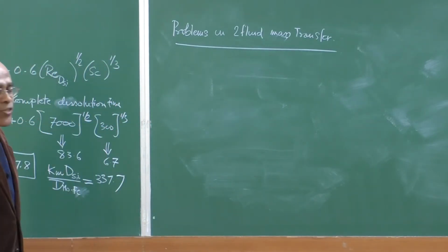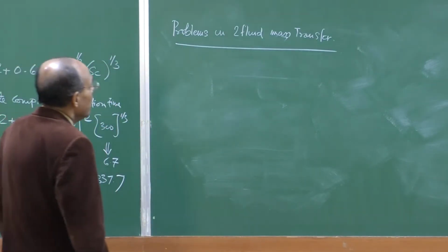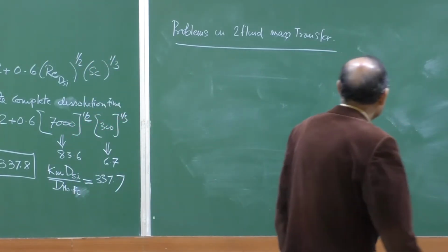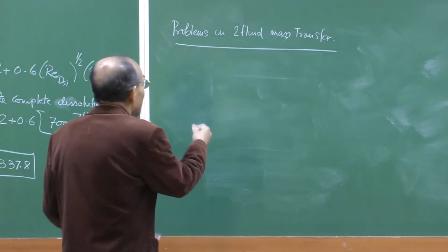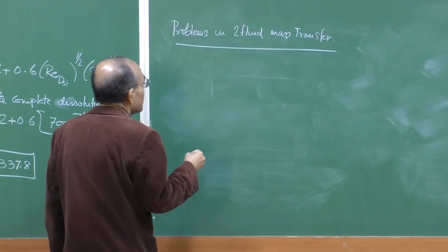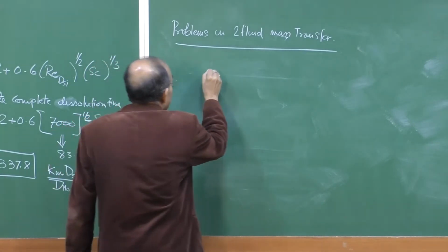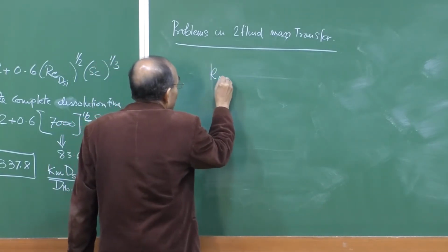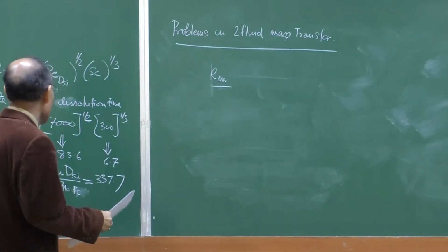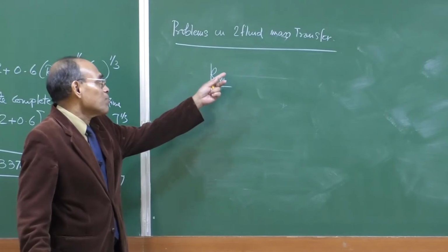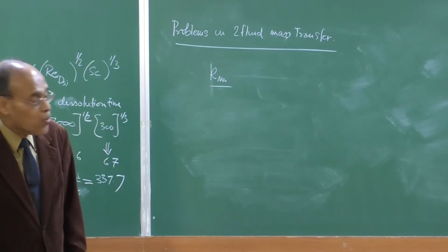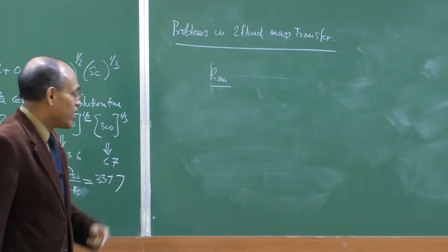The theory of mass transfer really does not change much. The whole procedure that one considers is a different approach for calculation of the mass transfer coefficient. So, the moment you calculate the mass transfer coefficient, multiplied by area, multiplied by the concentration difference, will give you the rate of transport, and by knowing the area you can calculate the rate of the transport.